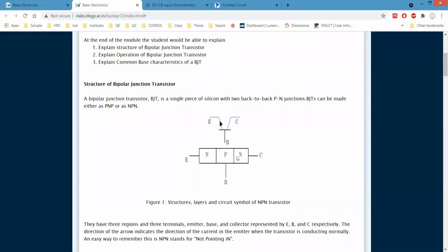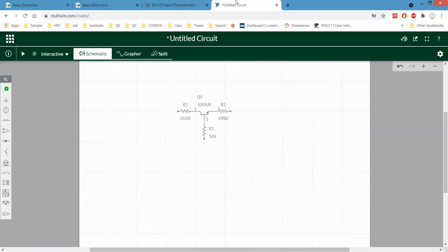That is why we cannot inject much more carrier in the base junction. That is one of the reasons. Also, you will come across a terminology called the punch through effect when you study the basic theory of the BJT, and you will learn why the base is intentionally kept thinner and why we cannot increase the base current to a higher value. Anyway.